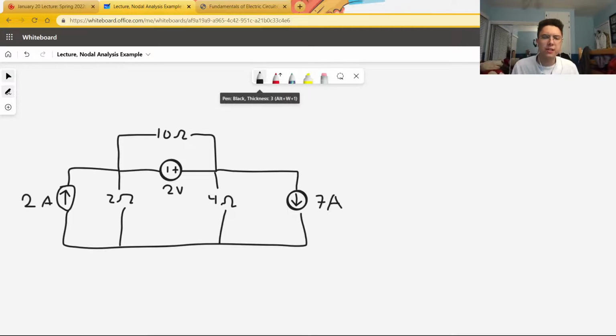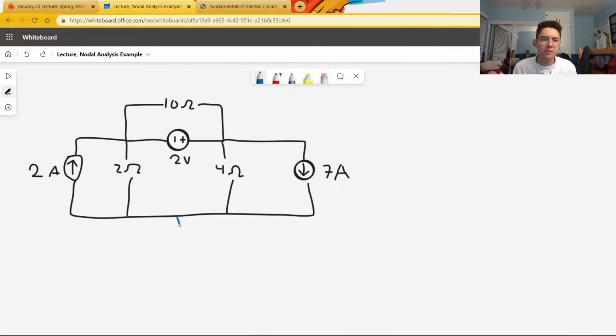In this lecture, we are going to perform a nodal analysis of a circuit that has a voltage source in it. The voltage source does not make things excessively complicated, it is just going to replace one of our usual unknowns with another unknown. Let's begin by selecting our ground, which is the first thing we do for nodal analysis, as our 0-volt reference voltage.